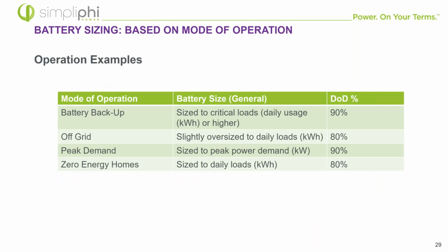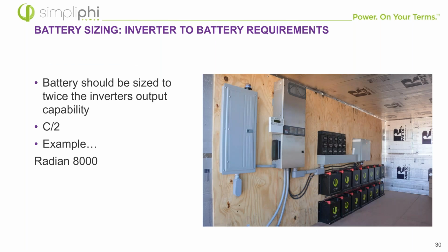So if you ever have any questions of what depth of discharge to use, feel free to reach out to us. Really, it's always going to be dependent on your mode of operation. But if you ever just need the base recommendation from us, we typically recommend 80% as the standard, without question.